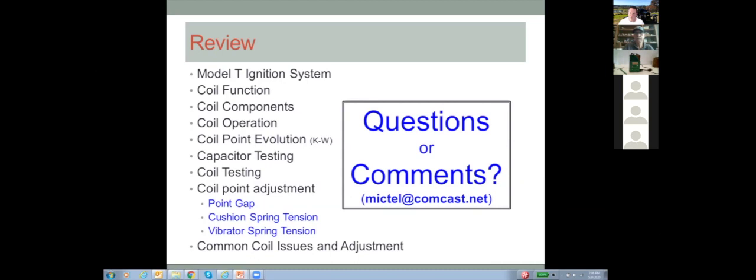There's a formula that you can apply to it, and it's actually to the square of current. The spark energy is 1/2 L i squared. So I is squared, so the more the current, the more the energy, to the square of the current. So current is the dominant factor as far as spark energy is concerned.